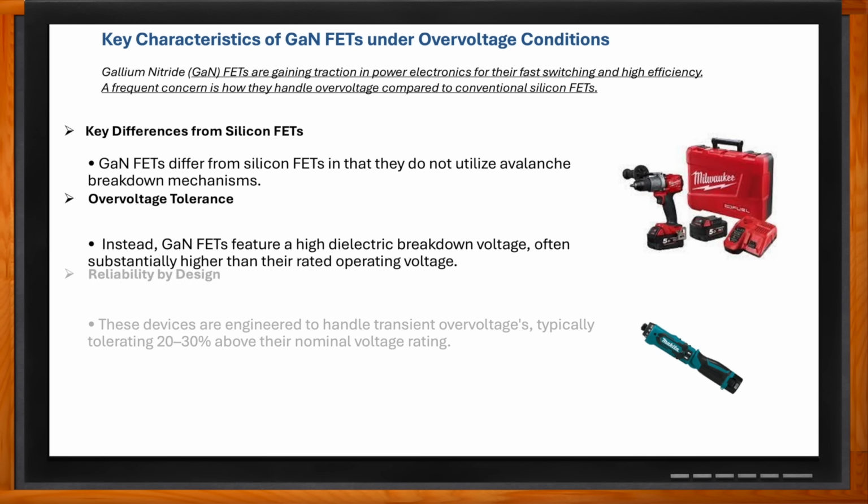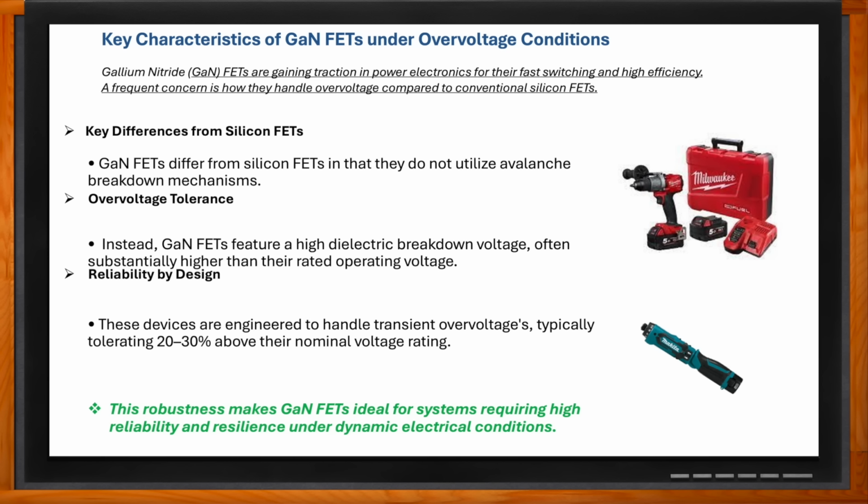The question is how repeatable. So some manufacturers actually state that in their data sheet. Nexperia, we're a little more cautious with something like that. What we do, we actually recommend protection on the output, that if you do, let's say, overvoltage the part, we have a clamp on the output that it will not permit to go, let's say, above 110 volts, for example, or 100 volts even.